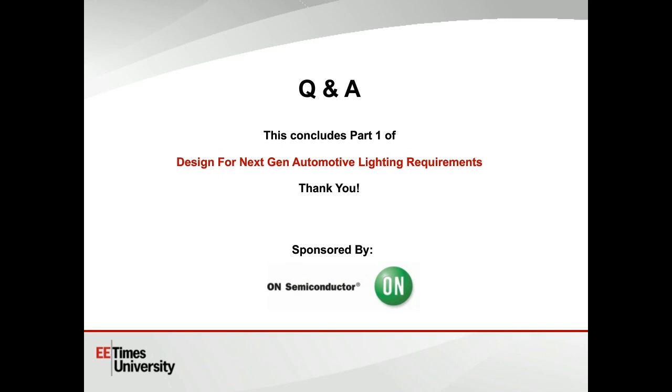That would mean that the manufacturer can detect the failure, there are ways of detecting this, and alert the driver to say, hey, this has reached the point where, with a suitable safety margin, it's time to replace the LEDs. And secondly, while still alerting the driver, they could switch operation to another LED or use one of the other LEDs in the LED matrix to make up for that lack of light.